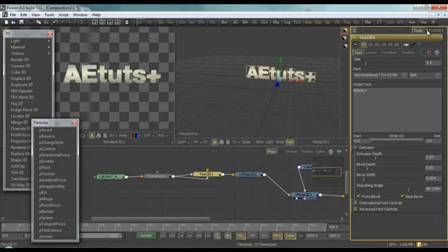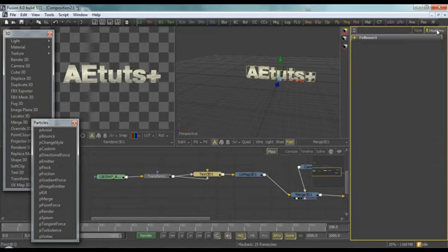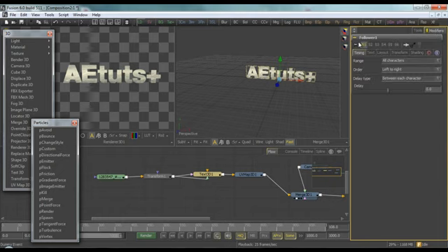So an icon appears, an activate icon, that considers this modifier activated, and we open it by pressing plus, and we will select the range all characters. It's very important, characters between each character, and we'll set the delay to 8.